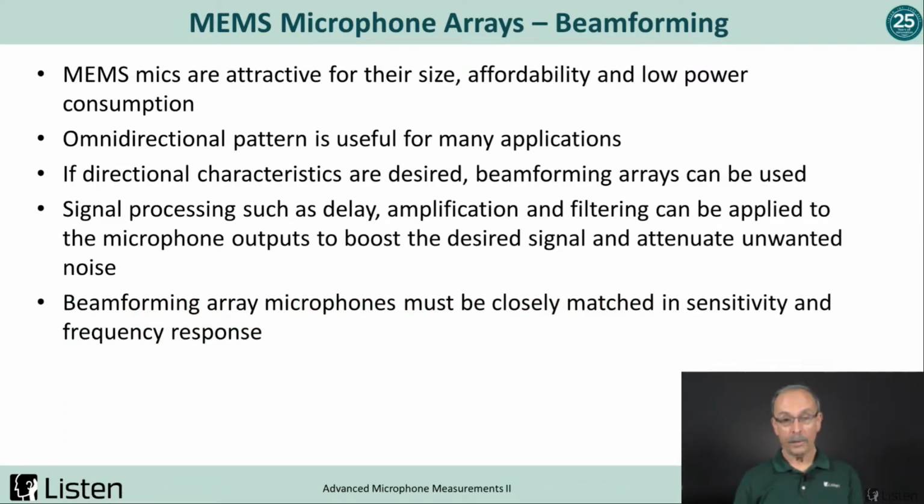The thing with beamforming microphones is that they must be closely matched in both sensitivity and frequency response. And MEMS manufacturers tend to do a pretty good job of achieving both of these goals. So if you're buying a MEMS mic from a reputable, well-known manufacturer, chances are that they're going to satisfy both of these requirements.